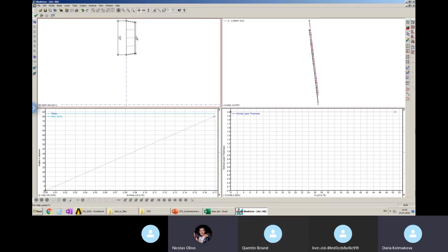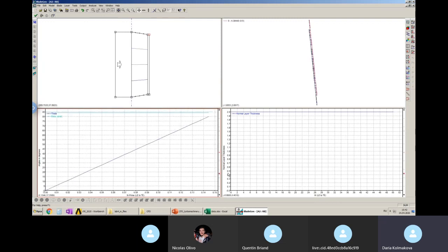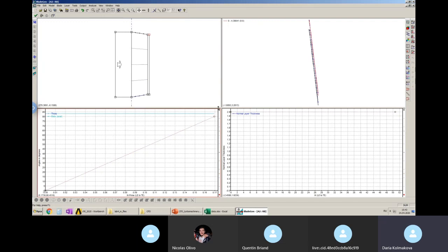And this line is exactly the line by which our two blades will be combined in the CFX project. So this is the first preliminary view of our blade. For both graphs, you can see on the right several points. The red point means that it's the active layer. The black points are the points in which we can correct the parameters of the layer, and for the gray points, we can just view the parameters of the layer, but we cannot correct them. Because we selected only 2 layers, hub and shroud, we have only 2 black points.